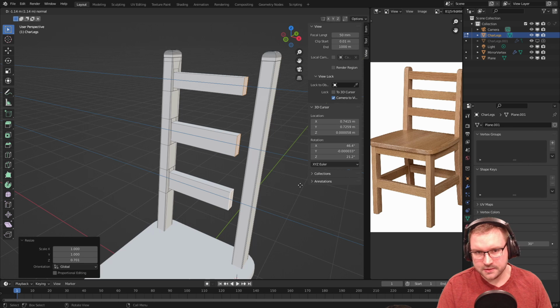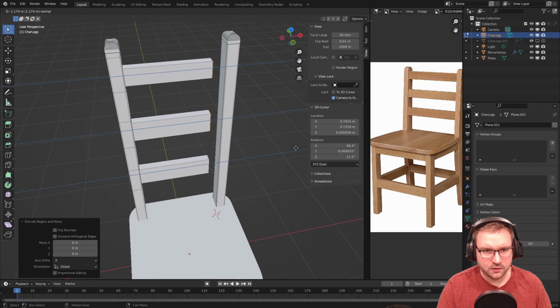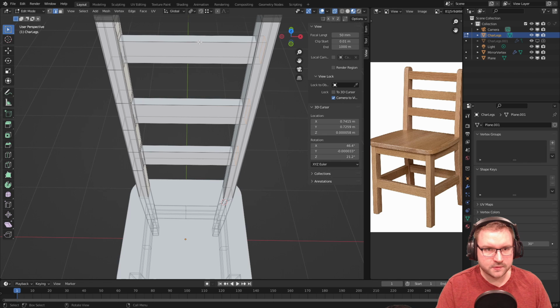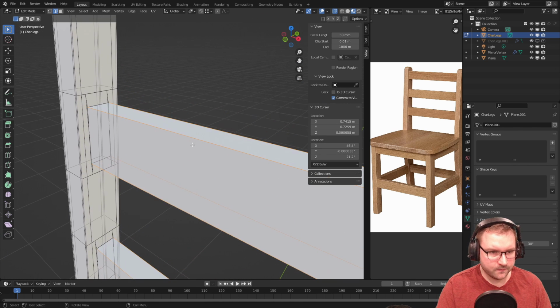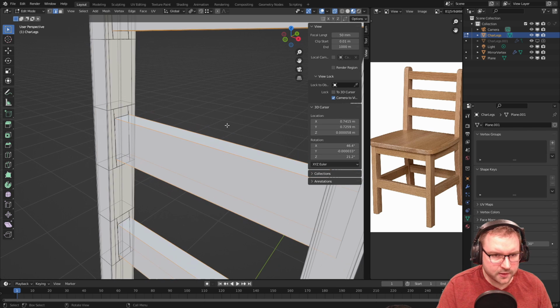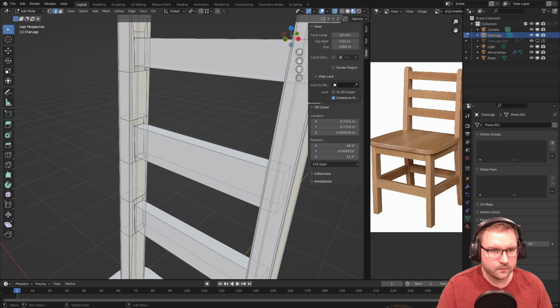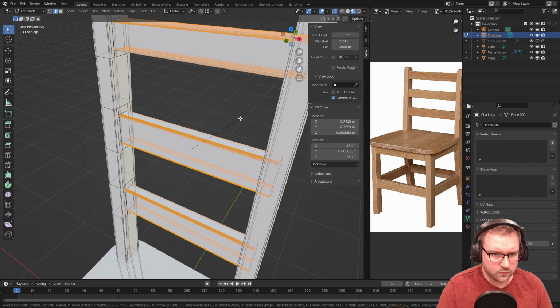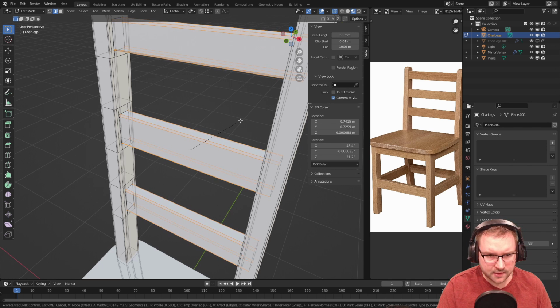Alright, I'm not going to have any fancy topology here. I'm just going to extrude it through there, just so it's hidden. And then I can bevel these. Should be nice and easy. Shift select all those and we'll just hit Control B. It's a nice single bevel here. Let's lower that. Oh, we need to apply scale to these, I think, maybe. Control A, all transforms. I want it to scale, right? Okay, so we're going to move on to texturing next, I think.